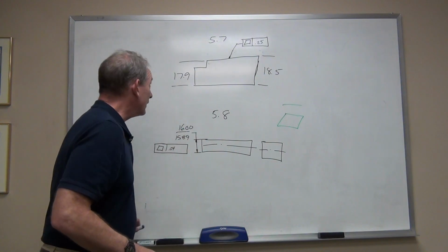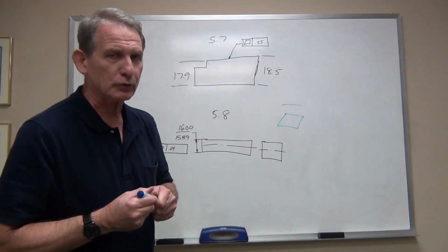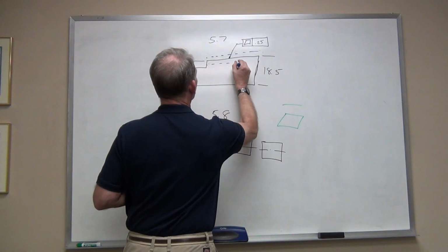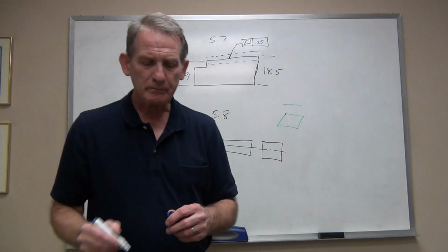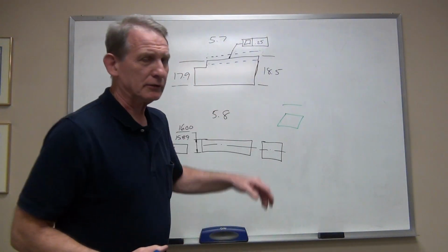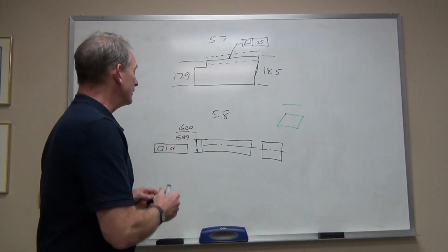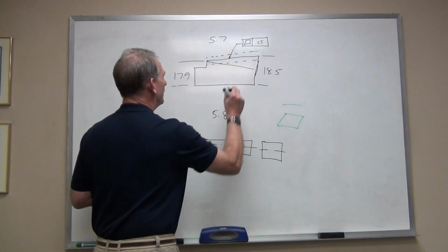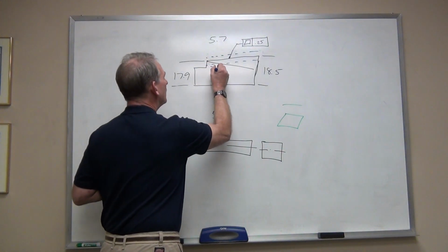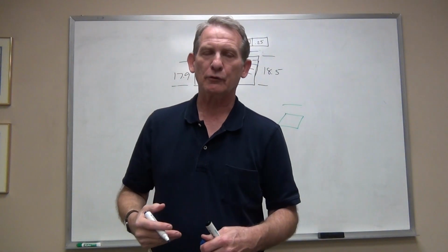And what that means then is that when we establish that tolerance zone, we actually have to sort of follow that taper. And that's perfectly legitimate because, again, these are size considerations. They have nothing to do with the flatness. Even if this thing was totally tipped, you know, something like that, we would still establish the tolerance zone wherever that surface happens to lie.